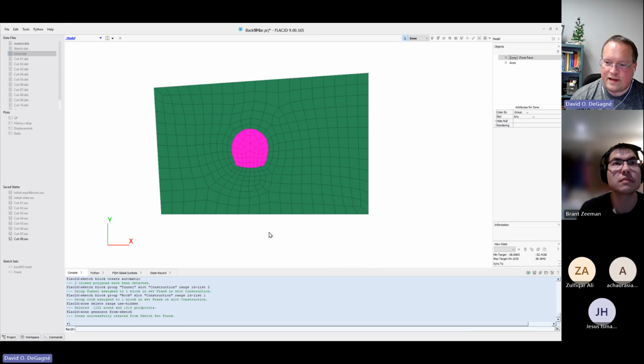Again, these aren't really the boundaries that you would want to have, but we've got some nice tools now in the model pane, which we're in now, where we can essentially automate the boundary conditions. It doesn't actually specify what the conditions are, but it lets us group them. So this would automatically get named to like west, north, east, south, I guess.